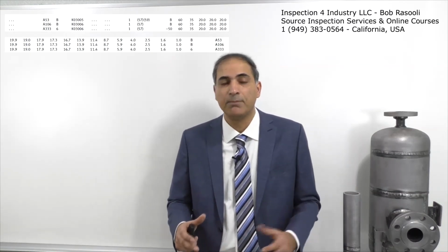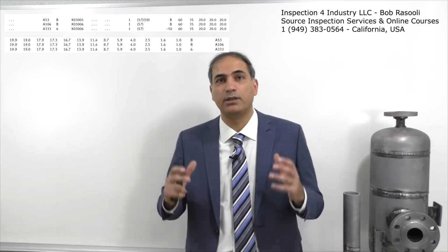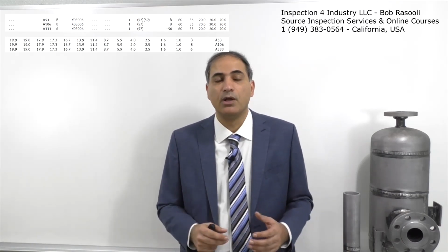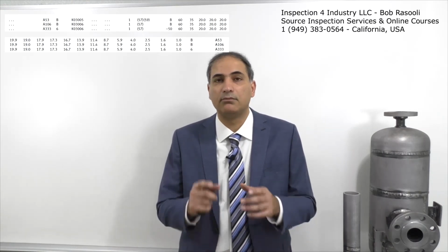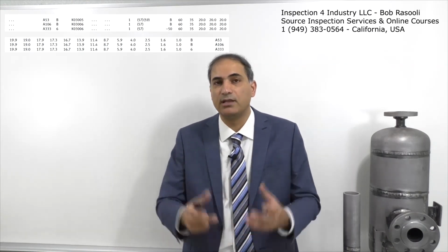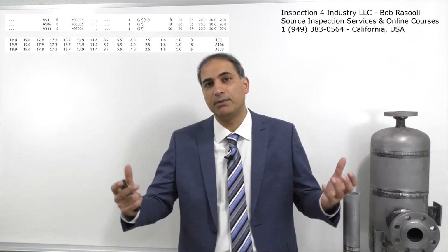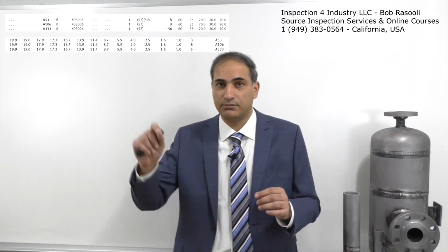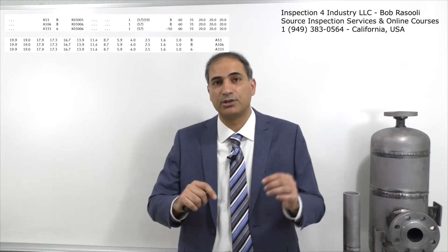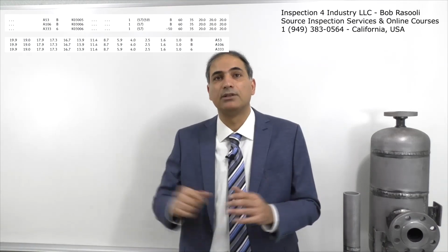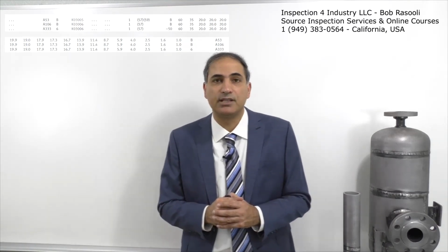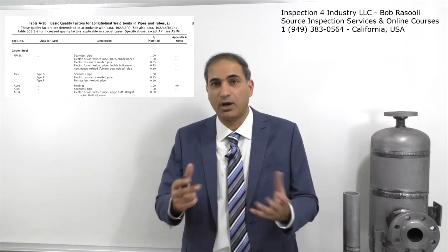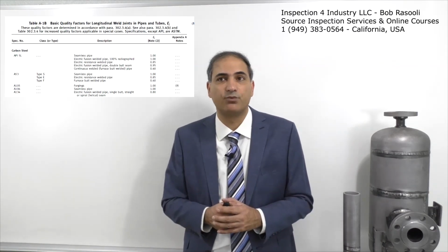In a chemical plant or a refinery, you are dealing with very high temperature services. So what we're going to do is read this S value, which I named the allowable stress. You go over there and there's a table, which is a combination of the material and the different temperatures. You read the allowable stress at that certain temperature, which is indicated in the problem that you're going to solve, and then put it in this formula.